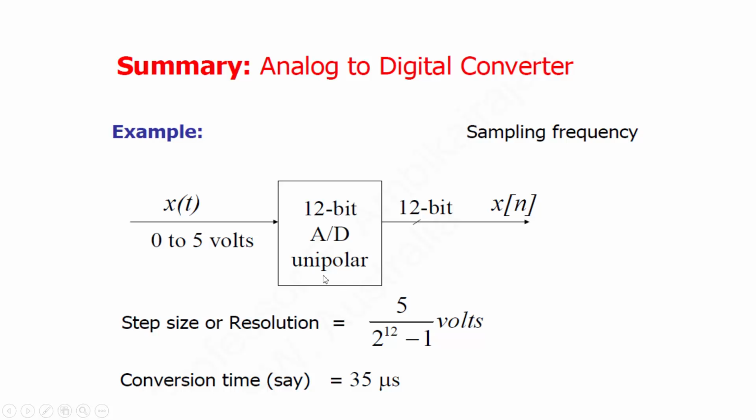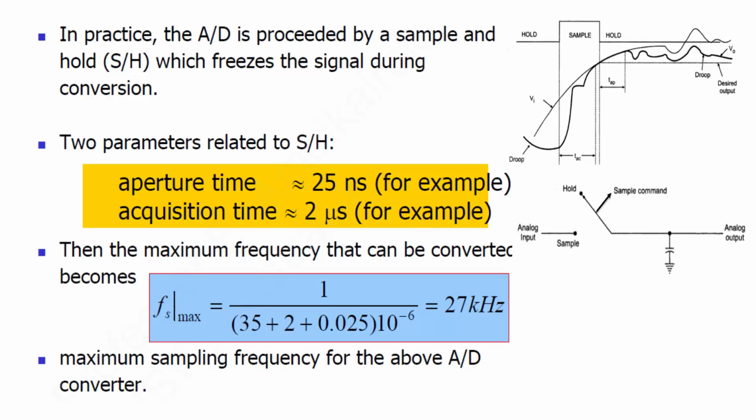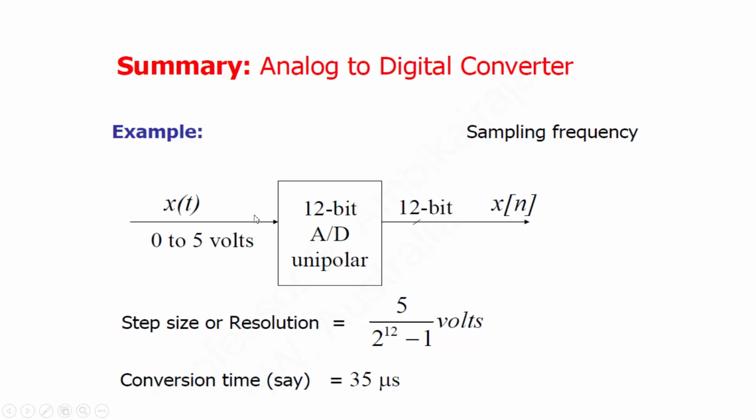You need not take the 2's complement of the rest of the half portion of the levels, so you will take all the positive values in the digital form. With every sample, because the A to D converter will have sample and hold, quantization and coding, 3 blocks in this one block shown here, I have already explained. After it goes through all those 3 blocks, the output will be a 12-bit digital, coded form, right?